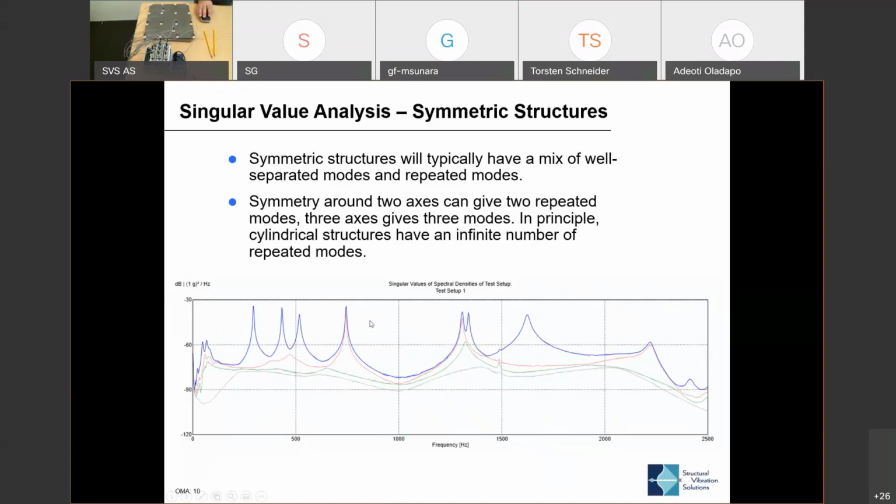This also repeats itself over here. Now you can again see two pointing up to this point here. And then there is an additional third one that is coming from the green one down here and then all the way up here and then down this way. So this way, by visualizing it, combining the different lines, you can actually see the different modes. This is also why this is called a mode indicator function.